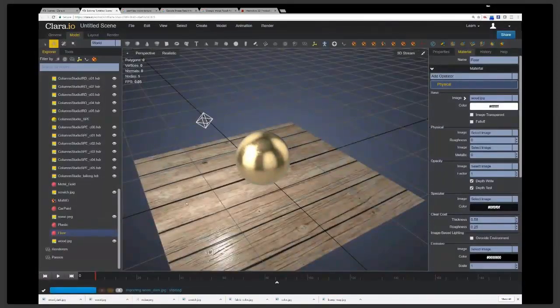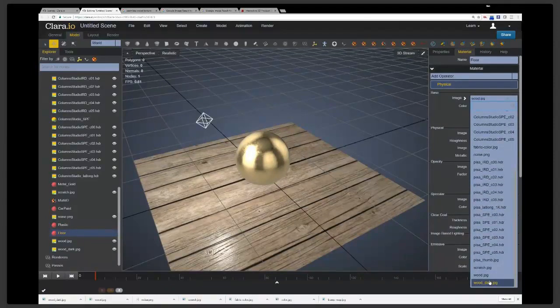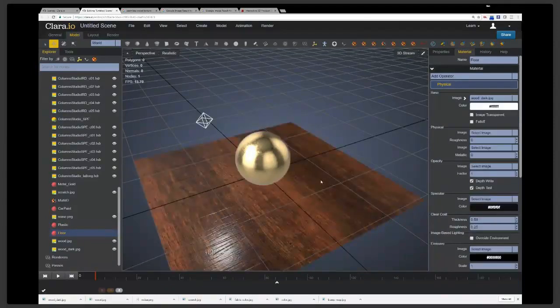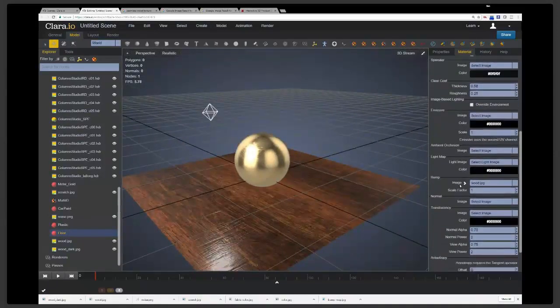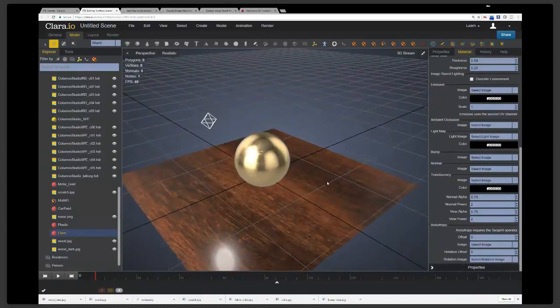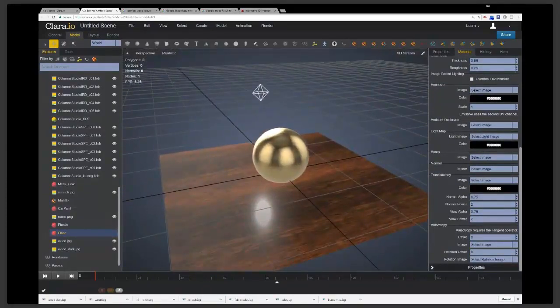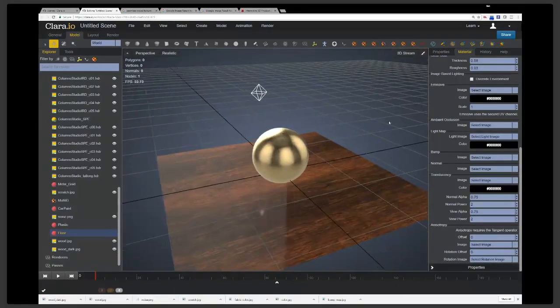Pull that in. Okay. We'll pull in that the wood dark here. And we'll get rid of the normal map or the bump map there because it's not really useful in this case. And what I would do, if I was making very expensive furniture that has a really good clear coat on it, is change the roughness of the clear coat and bring that down.